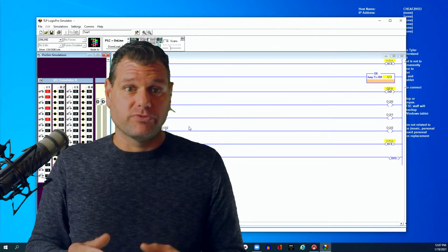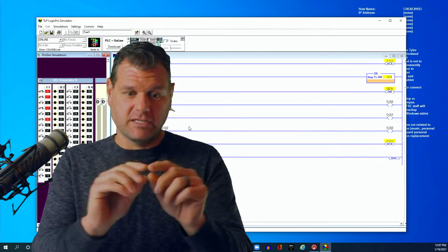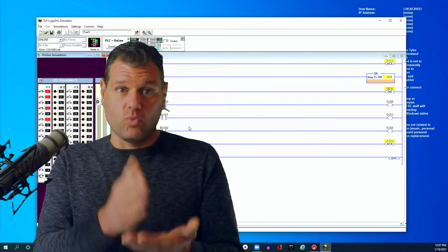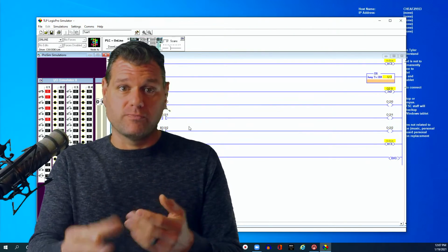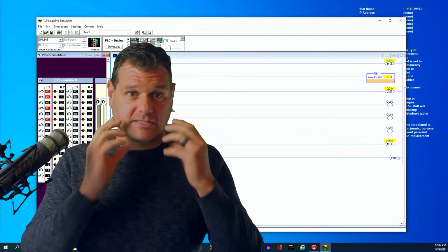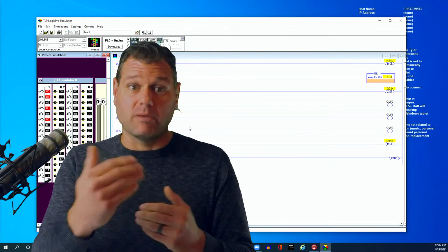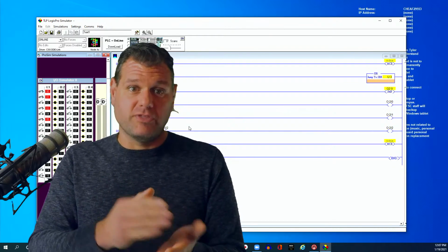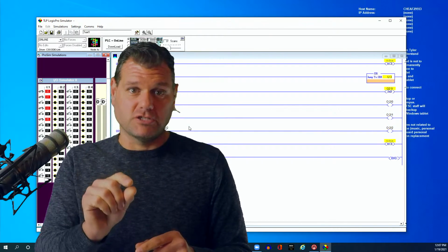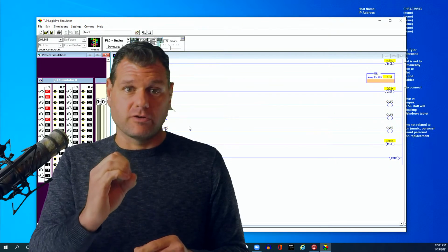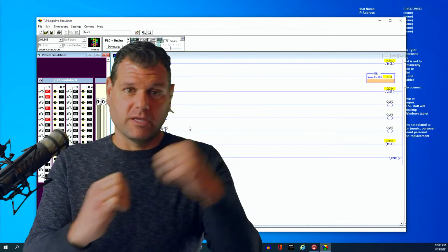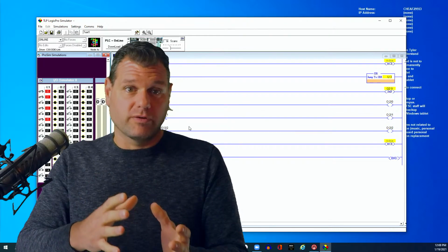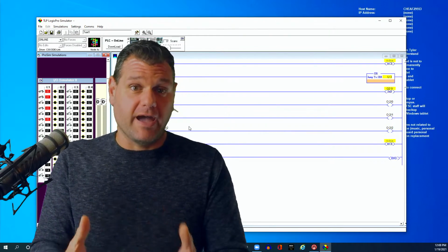Same thing happens here. There's a mask, which is basically a 16-digit word. It's 16 ones and zeros. If there's a one in place, it passes the information through, just like if we're not wearing any mask. It sees everything without being blocked. If there is a mask in place and in that digit location there's a zero, it's basically going to block it and say this information cannot pass. So whatever information was there last is what they're going to have.